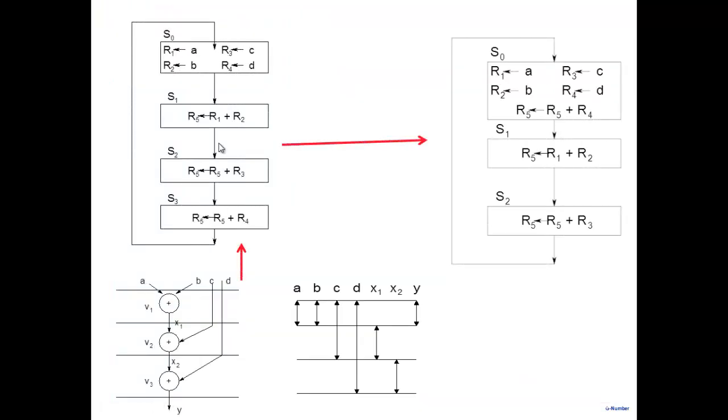We had talked about loop pipelining, but in this diagram we had not talked about it explicitly. Because this is creating a bit of confusion: if we have this and we say Y is folded back here, which is not true, right? Because if you add this particular state, then Y is available in this particular state, not here. So there's nothing inconsistent between this and this. This diagram is still correct, except that an unnecessarily extra register is being used, which we saw in the quiz. As all of you, when you did the quiz, found, it has extra registers and you can reduce it, okay?